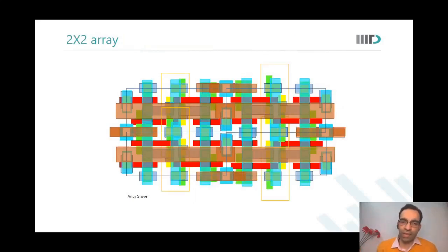So as we were talking about putting cells in MX, MY and X, Y locations, we get an array. Do you see this ground? This was the ground that is now shared with the adjacent cell. This is the word line that is shared across memory cells and so on. So we can make an array through which this sharing enables still higher density.